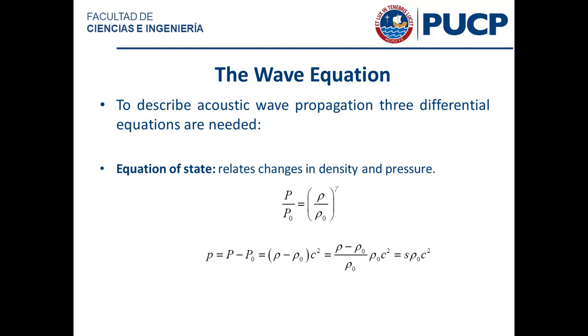But the point is that as good engineers, we want to always come to solutions of equations that we can actually analytically derive. And it is very, very challenging to come to a solution or a closed form solution of the wave equation if the equation of state is not linear. The only way that it can be linear is if we were to be dealing with an isothermal process. But for better or worse, ultrasonic wave propagation is much better modeled as an adiabatic than an isothermal process,